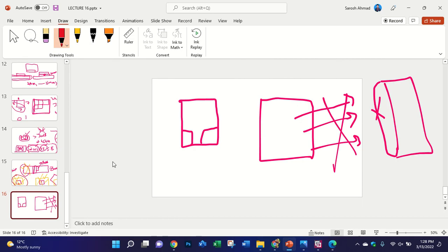Dear Tariq, do you have any question? You are saying something. Mr. Ahmed, is all this design that you make to improve the gain? Yes. It will surely not affect the frequency band. Suppose your frequency band is this one, the frequency will remain the same even if you use the full ground plane, but there will be no increase in the gain, because without a ground plane, how can it reflect the radiation to the other side of the antenna?